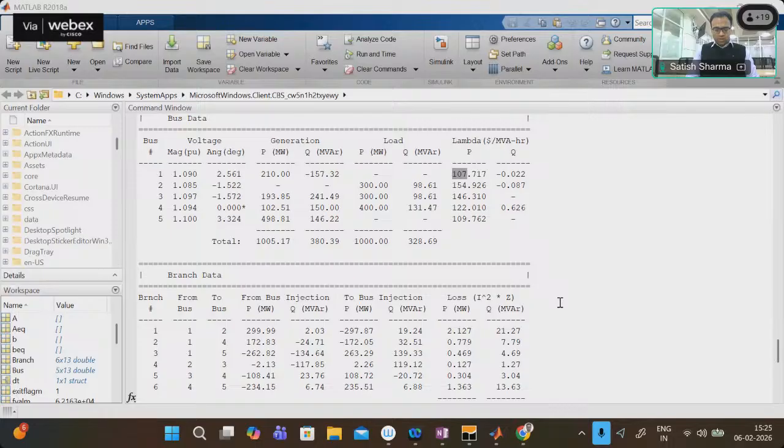They are not some software where everything is hidden behind the curtain. All the files are .m files, MATLAB m files, and you can see each and every file, what kind of code is being written there, so you can edit and update those codes on your own. So I would recommend for ACOPF, DCOPF, do not write your own code. These are just basic fundamental blocks, on which we can build and write our own code for our other complex problems.